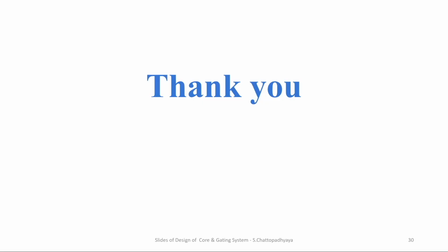And that's all for today. We have discussed different aspects of the core making process, what their role is, how they are placed, how they are made, and the overhanging positions, the chaplets and the chills. We have had a detailed discussion of the entire making process of core sand, what its features are, its similarity with molding sand, some features which are slightly different, and what its utility is. And we have seen those products as sample cases where they are utilized to manufacture engine blocks and other things, as a very crucial method of generating hollow sections in the cavities. Thank you.